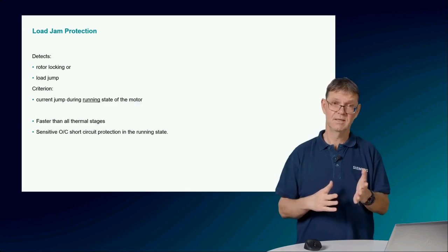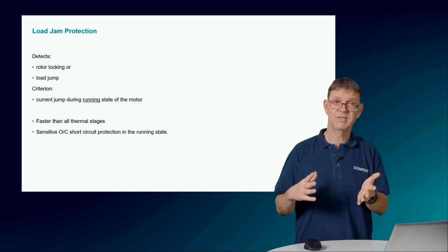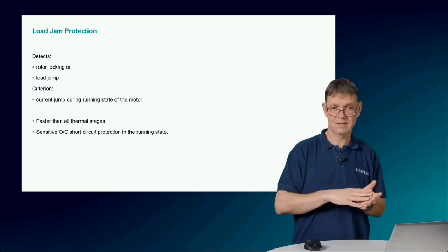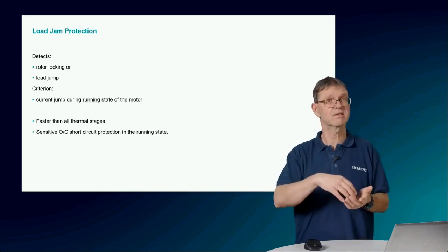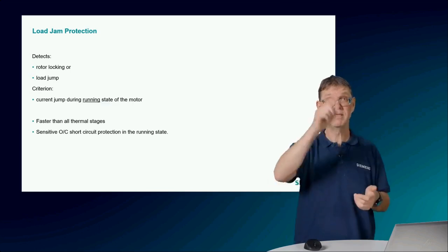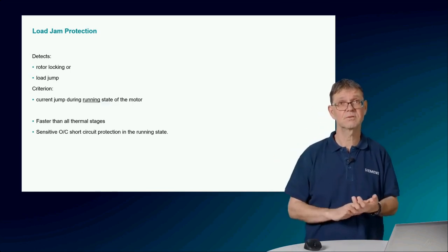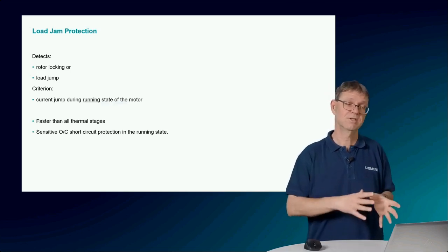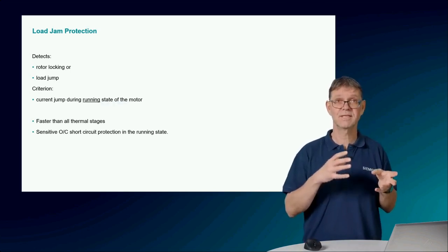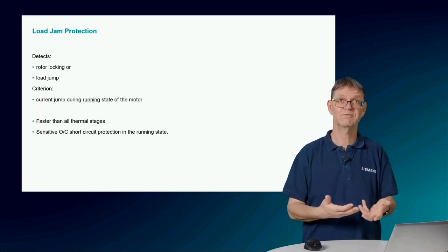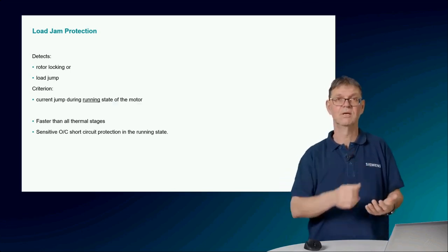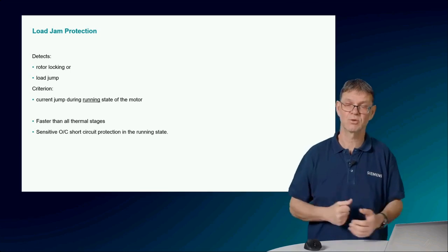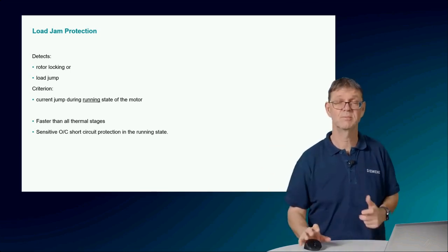Again here, if we have a switchover, fast switchover, then I take away the voltage and then I bring back the voltage, then I get also again peaks of the starting current or the restarting current for the motor. So we have to avoid that this function is active also in that state. Again, therefore we have the slowdown state to go away very fast from the running state in case of such a dynamic switchover. Okay, but that's just as a repetition apart.